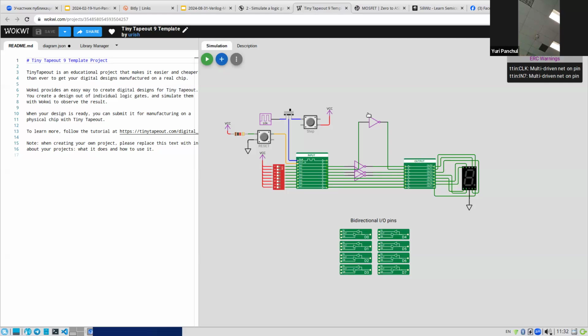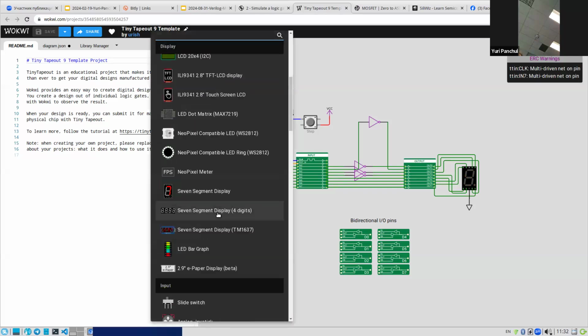Yeah, okay. So basically, first he was showing a basic editor of silicon layers to build a transistor, and then he showed this schematic editor called Wokwi, how to draw a schematic diagram and how to simulate it. In the simulation, you can run the clock, and you can turn buttons on and off, and you can build some structures here. So you can stop the simulation, and then you can add, let's say, a flip-flop.